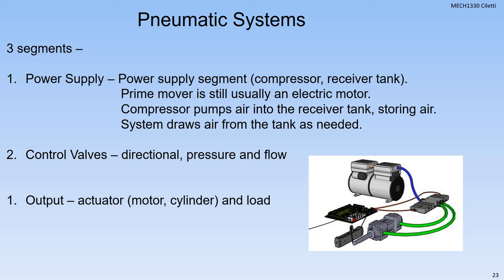So that is an introduction to the basics of pneumatics and the gas laws. We had Boyle's law, Gay-Lussac's law, and Charles' law, and we've used all those different laws that isolate temperature, pressure, and volume. We convert them into the combined gas law, so we were able to use that depending on the system. We talked a little bit about adiabatic systems, and lastly we talked about how we calculate using a vacuum system to pick things up.